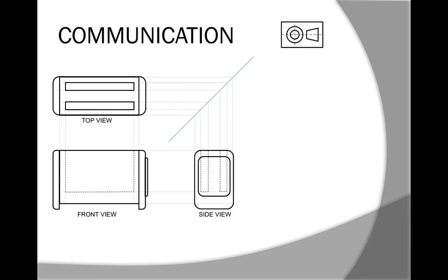Now, you can see my light, thin lines. They're my construction lines. That means that everything should line up. Now, I've used these dark dotted lines. Those lines should be a little bit darker. If I was going to update this, I'd make those dark dotted lines. That's hidden detail. That's showing that there's something going on in the inside. And the same thing about hidden detail here, right? To say that I've got two slices. I've then got this panel on the outside. I really should be able to see that panel up here. I'm a bit disappointed in that.